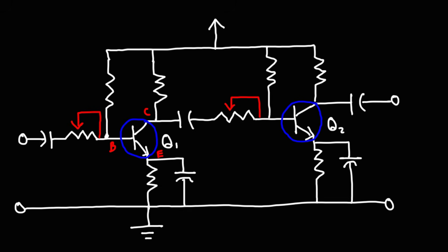Now, in this video, we're not going to focus too much on the math, but more on the concepts behind this particular circuit. Now, the first three capacitors that you want to be familiar with are these three capacitors, C1, C2, and C3. These are coupling capacitors. They're designed to block DC, but to allow the passage of an AC signal or a voltage varying signal.